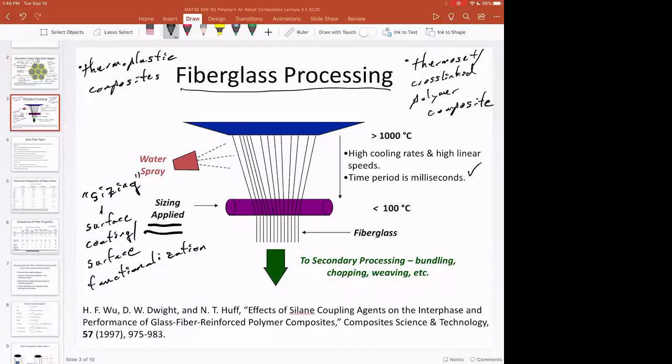We looked at a carbon fiber mat when we introduced this topic, but all of these materials have a surface coating applied to them that's usually done when they're made. There are all sorts of different types of glass fibers or carbon fibers made, and they come with all different sorts of surface coatings. You can look up in material supply catalogs or tables of fibers and fiber types that are available. It will often say what surface coating it is, because the surface coating has to relate to whatever matrix you're going to use.